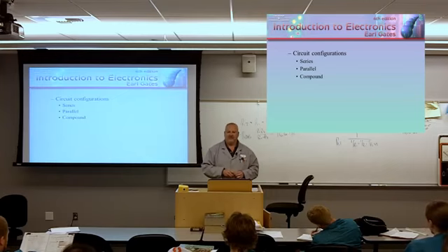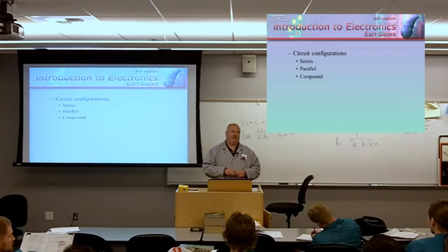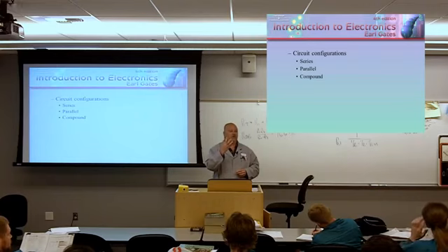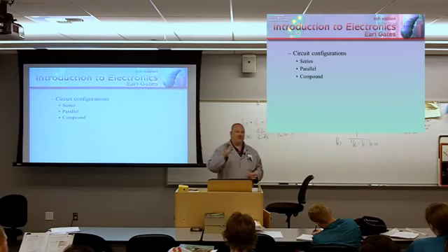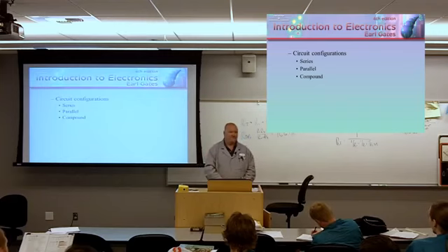Any questions out of this chapter? You add up the resistors or you just divide them by? In parallel, yeah, you've got to divide it out. So if I've got 4 100 ohm resistors, it's 100 ohms, 100 ohms, 100 ohms, 100 ohms. 100 divided by how many resistors? 4. 100 divided by 4 equals 25. I should have approximately 25 ohms across that circuit.